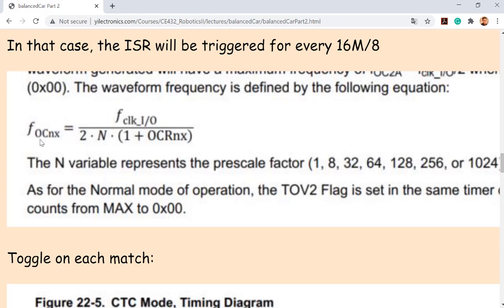After the PID error is updated in your main loop, so it knows the new position, whenever it gets interrupted again, it rotates the wheels again using the new PID error value.